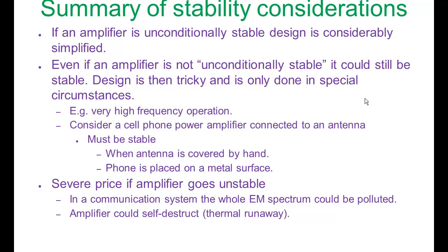We should qualify that a little bit. If we used feedback, we could of course create an oscillator. What we have considered here is the active device on its own without feedback. So if we do not apply external feedback, at 8 gigahertz our amplifier will be unconditionally stable no matter what we do to the input and output matching networks.